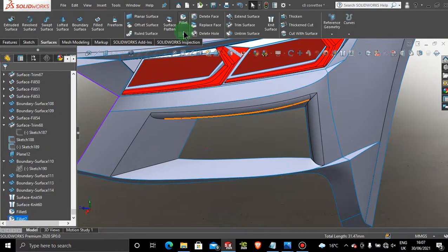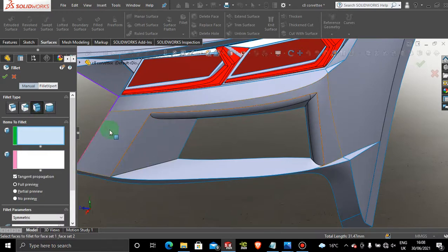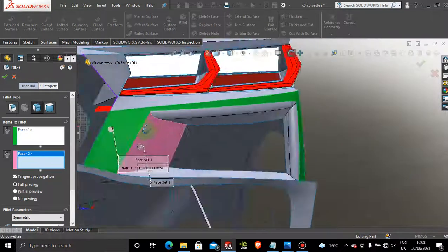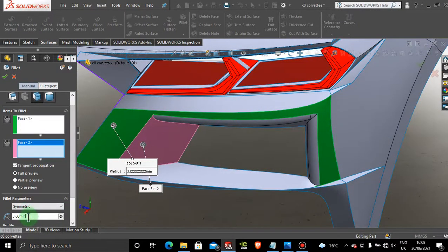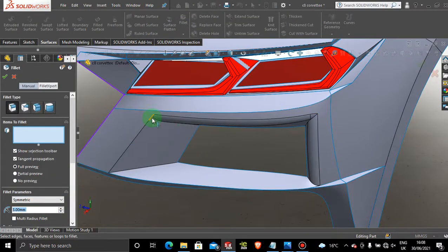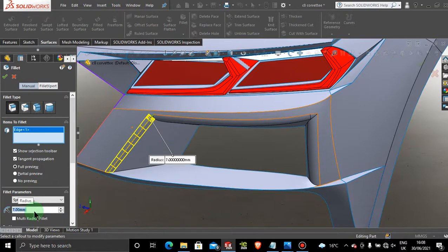Let's try that again. Let's try a fillet, right? So it attempts to fillet with this side and then this one. And they're both facing inwards. And let's try 5. Let's flip these arrows. And still not all right. So let's try again with fillet. Okay, so 7, 9. Okay, let's try 10. Okay, 20. All right, there now we're getting there.